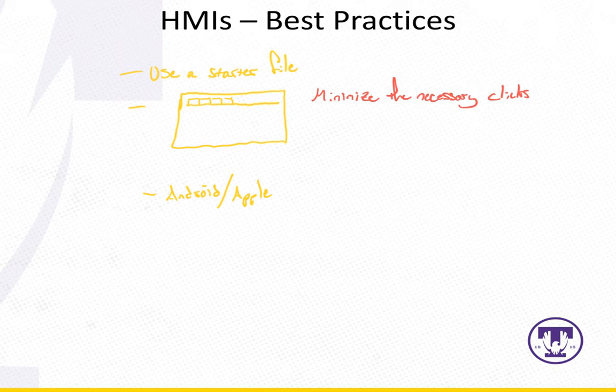Now, that's all well and good and helpful for when you're creating a large-scale HMI system, but in this class, you're not going to really have time to do that. So instead, you're going to spend your time creating HMI pages, a single page. And when you do that, there's a couple of things you want to keep in mind. Number one, you want the page to be self-explanatory. So it shouldn't be true that they need an instruction manual to be able to use the page you have created on the HMI.